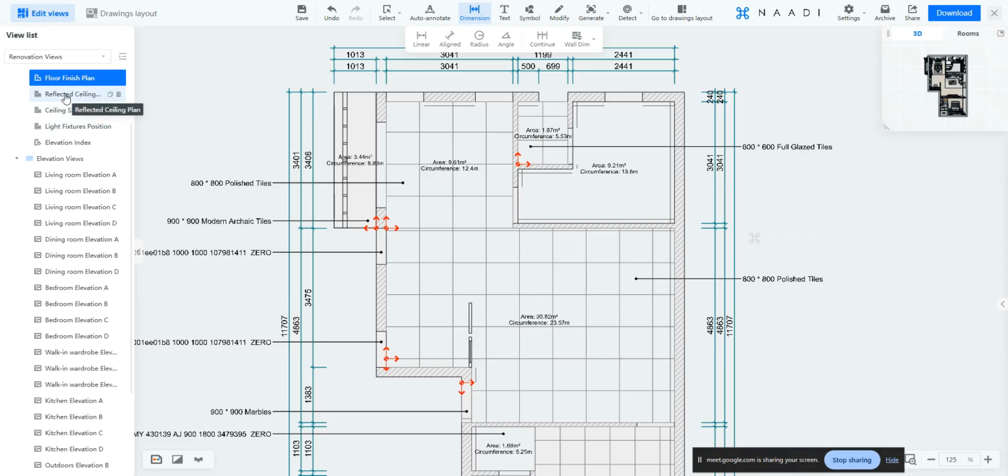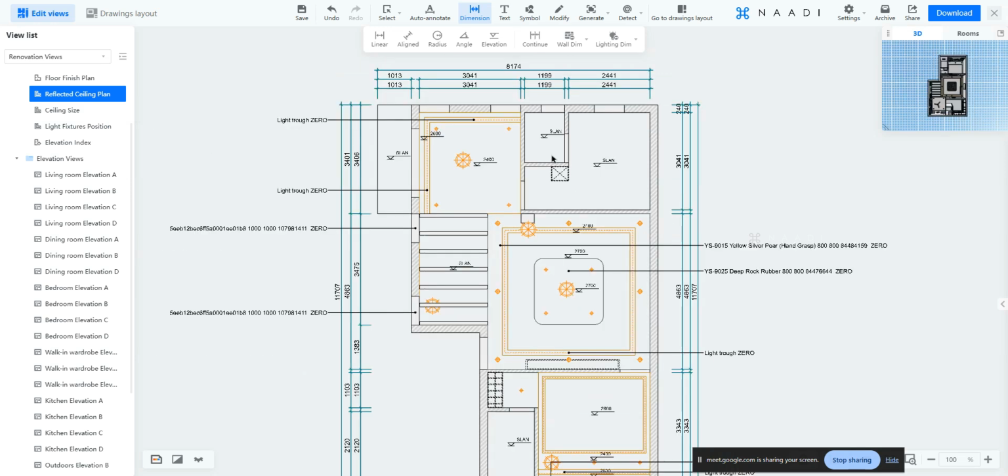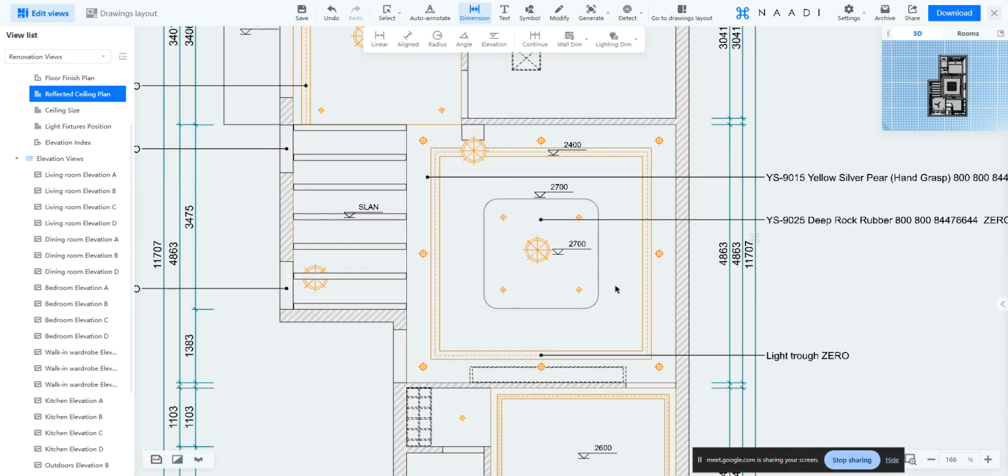Your fourth type of construction drawing is your reverse ceiling plan, which is your RCP drawing. Okay, yes, you could also generate a detailed RCP drawing, your ceiling design here itself. Okay, the thing is you have to properly design that ceiling using your ceiling editor, where if you want to add an extrusion, cove lighting, everything need to be properly added. If that is modeled there, then your RCP drawing is just a matter of seconds here.